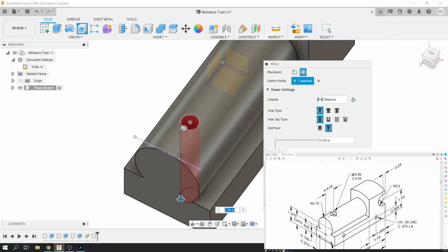Now here is the description of the hole type. Okay, you're going to do a simple hole, just like what I have on my screen. This is your depth, and it shows you like the picture of what you're defining as a side view. So this is your depth, and it shows you in the picture in the drawing that the depth is supposed to be 0.25, so change that number to 0.25. And you can see the preview as you're changing these numbers.